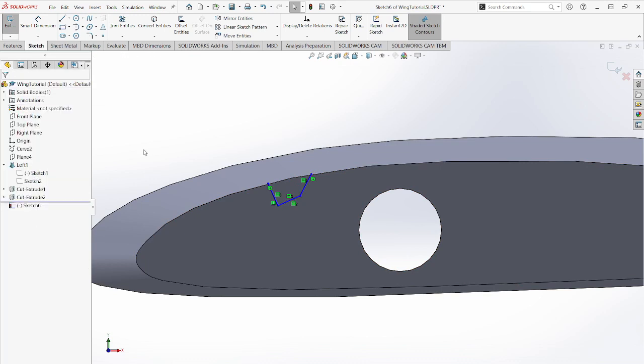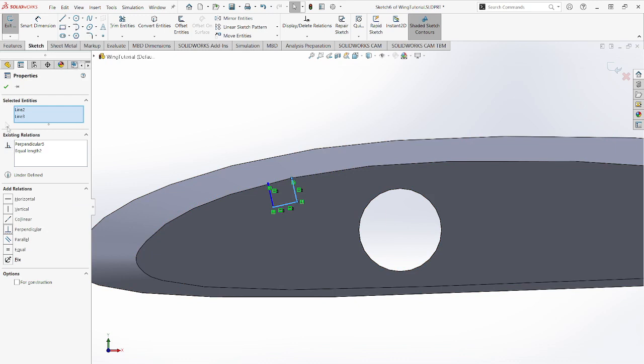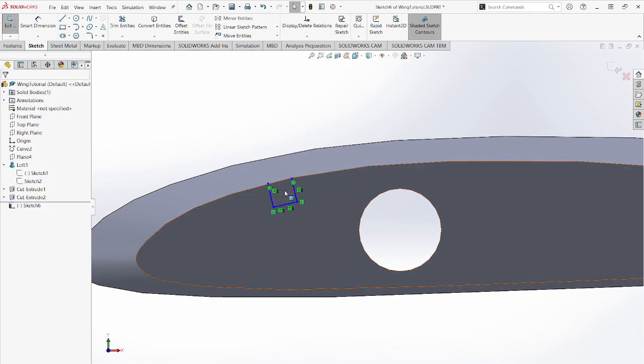And you might be asking, well, why not just make the entire square in one go? That's because if you were to make the entire square in one go, and then loft it, extrude it to the next side, it will likely leave a little lip of material on top. And that lip of material is undesirable because it's not reflective of reality. It makes things complicated for the model. It looks ugly, and we want to get rid of it, right?